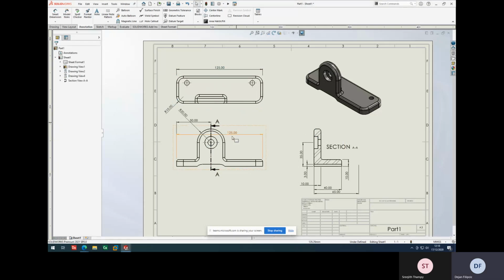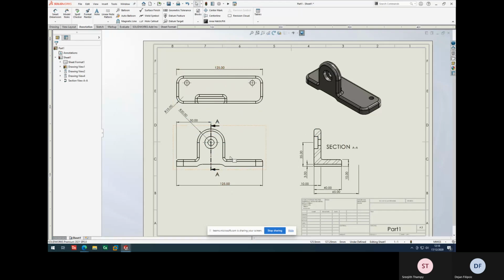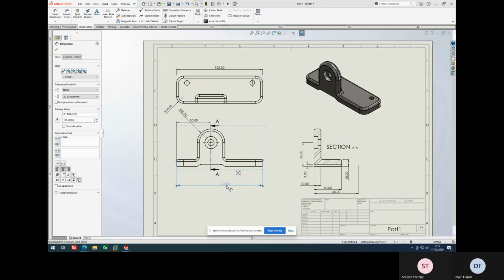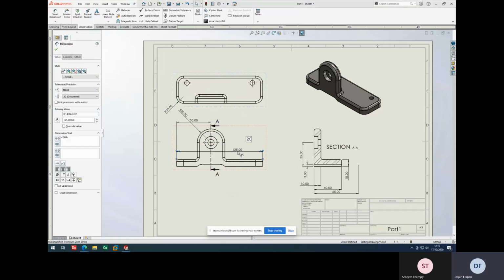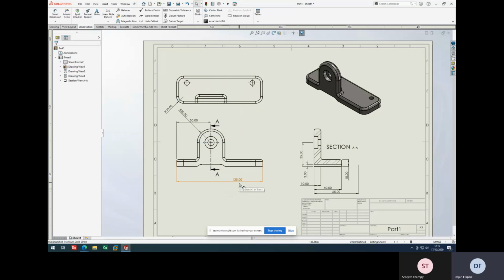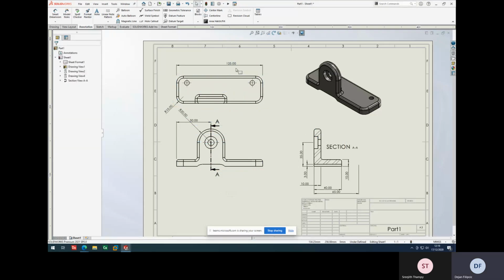So the basic command is, if I press control, drag a dimension and put it in the other view, it will be copied to that particular view. Which is valid for everything. When you drag features, it also copies the features. If you do it with parts, it will duplicate parts. Control will always create a duplicate. Now I have shift moved, so it has copied it. So I can bring it back. I press shift, I move it, and I bring it back to this view.